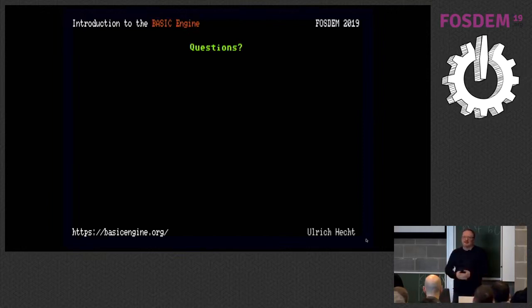You would need a new graphics driver. I guess it would be possible. But you would also run into a scarcity of resources on the microcontroller. It doesn't have a lot of I/O, so that might be a problem. Possibly with an LCD controller that also attaches to SPI, that might be possible. But again, you have to change the hardware for that. But in principle, yes.